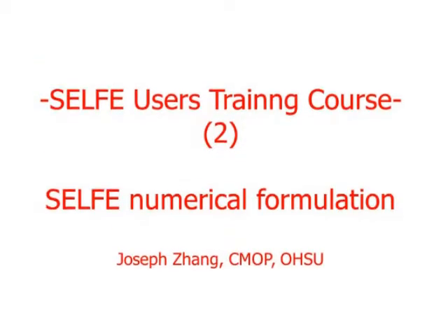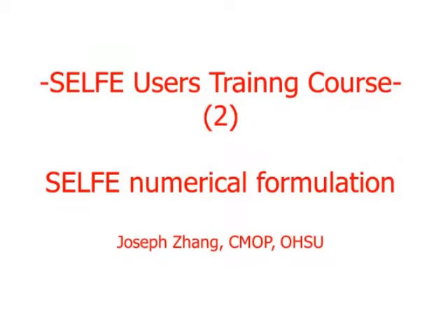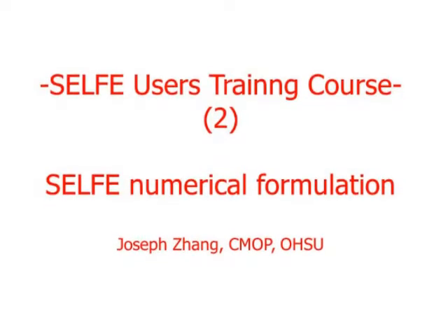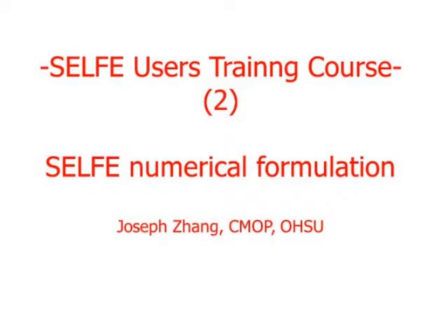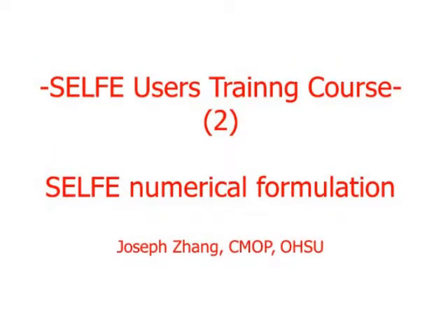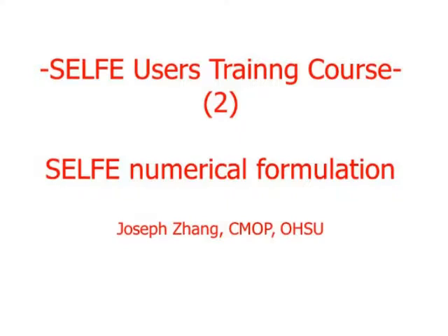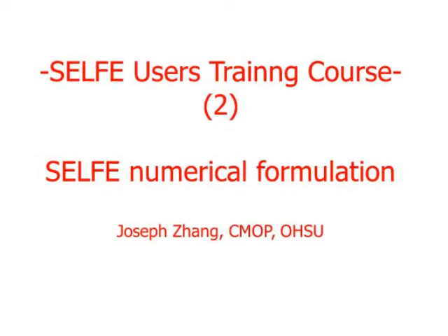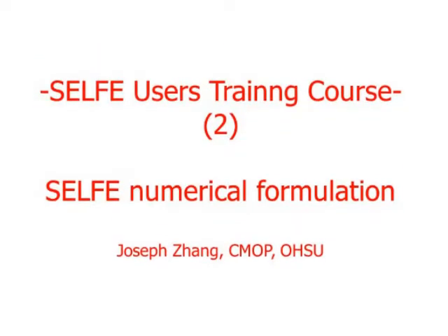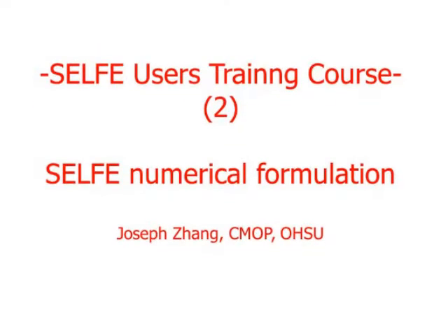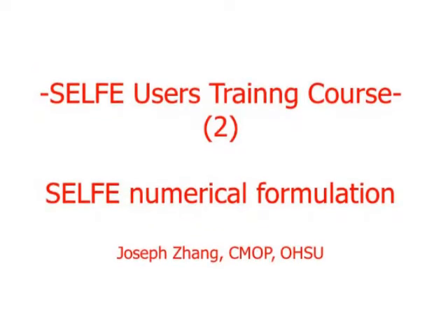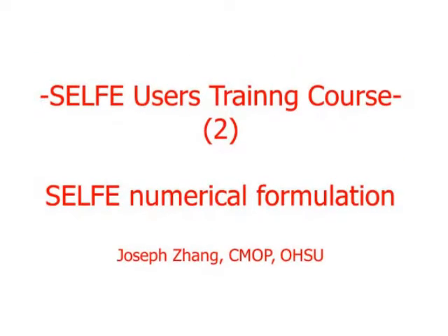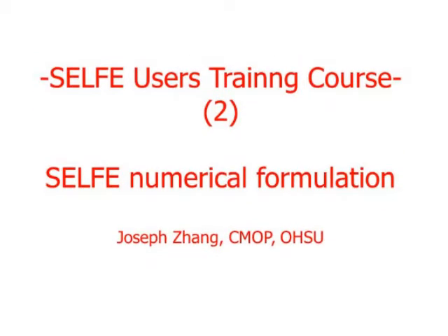Then you evaluate the variable at this position at the previous time step t. Of course, there are lots of details in ELM. Many people actually did a PhD thesis on ELM. But an important aspect of ELM involves how you do the tracking. You can either use the simplest backward Euler method, or you can use something more sophisticated, like a fifth order embedded Runge-Kutta method.